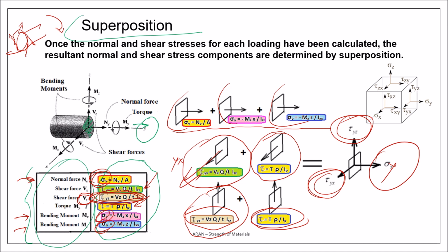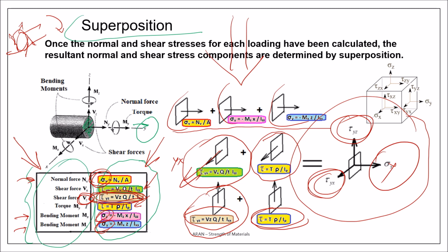This is how, when you know the forces and moment, you determine the stresses caused by these forces and moments, how you add them together by superposition, and how you find the stress state in a point.